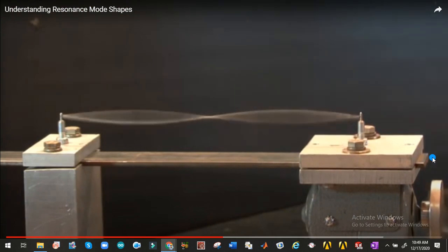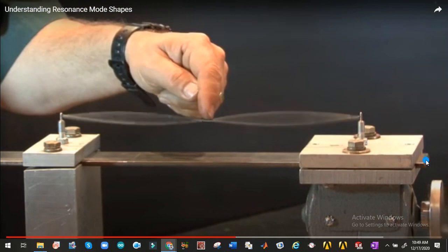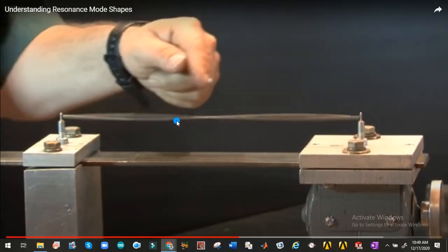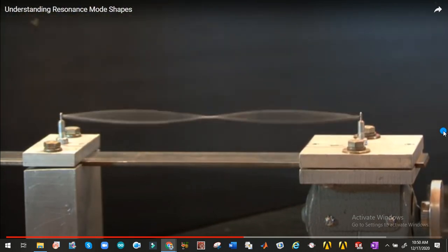Remember, with resonance, if we're going to insert a brace, we need to brace it at one of the antinodes. If we brace it at the nodal point, it has little or no effect. Yes, now you can see that if they are providing a stiffness element on a node, it has no effect, and if we are providing a stiffness element at the antinode point, then the whole vibration of the system mostly dampens. Antinodes, we solve the problem.